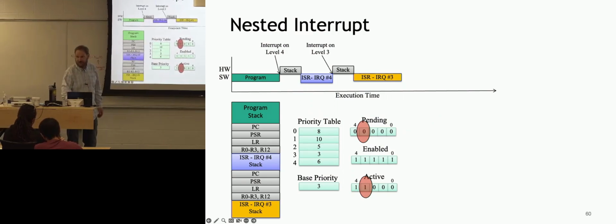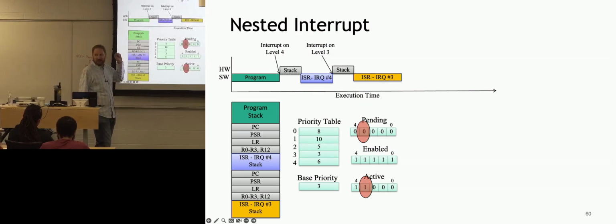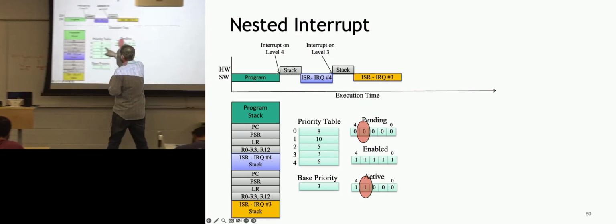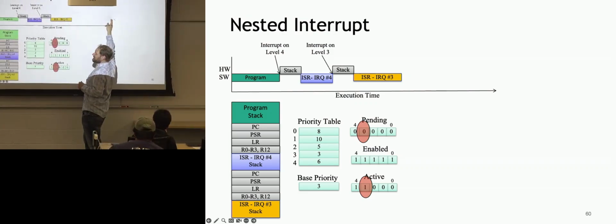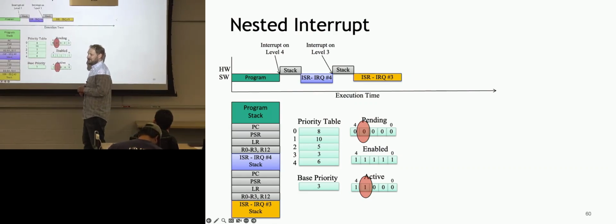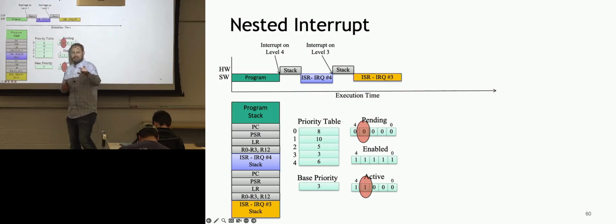The thing is only high during the stack, right? It never goes back high even when it's being interrupted by the next one. Pending goes high when you're not in active. So say I've got IRQ 10 here. I have to do all this other stuff first. It's going to be pending until I get to it. So it's not just stacking; it's when it hasn't been serviced, basically. When it's being interrupted by another interrupt, it doesn't go back to pending. To be interrupted by an interrupt, you must have been active, and when you're active, you transitioned out of pending into active. So that case can't exist.